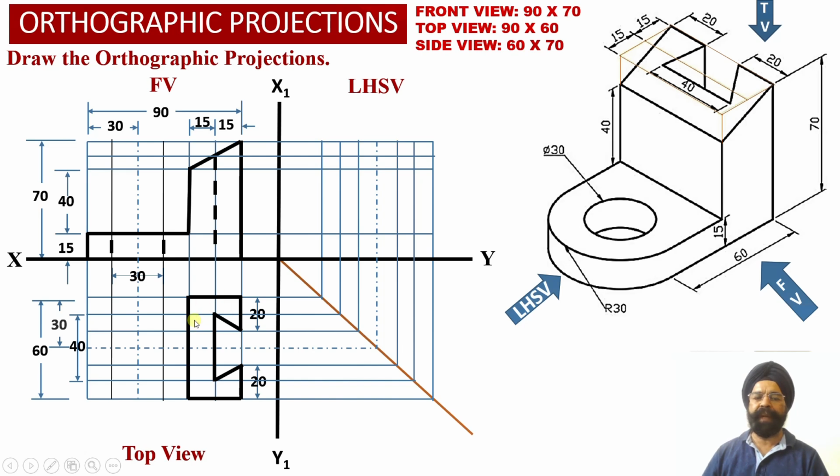So we have been able to obtain the apparent shape projections corresponding to this vertical web top surface. Now since this top surface of the horizontal web, which is our element number 1, is parallel to the horizontal plane, we will be able to obtain the true shape projections corresponding to this horizontal web into the top view projections over here.